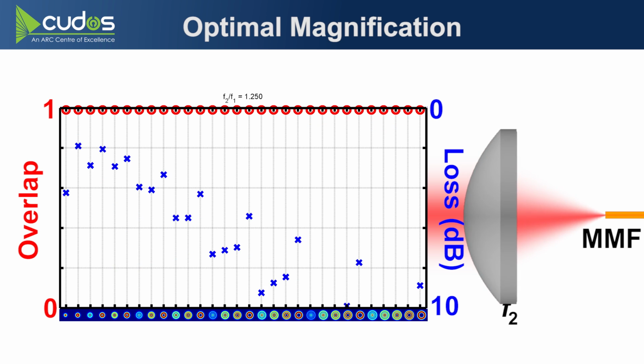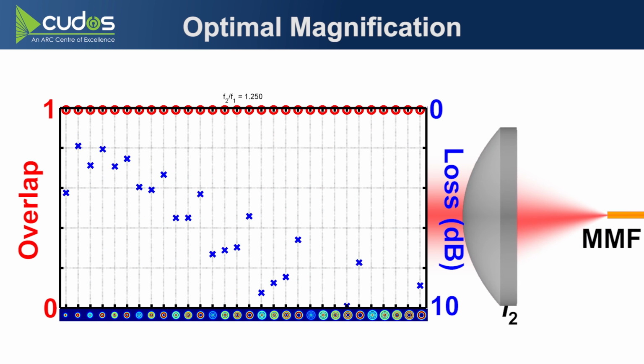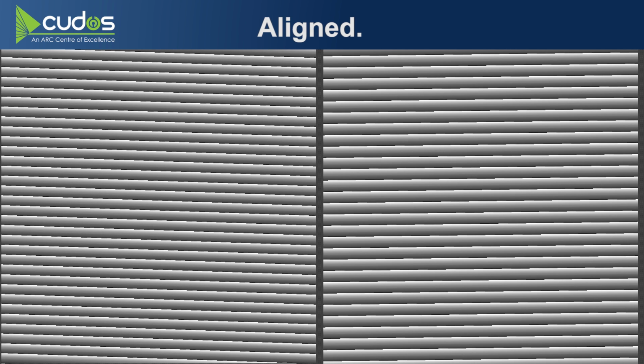Another convenient aspect of an SLM is that it allows you to perform a lot of the fine alignment of the system in software without moving parts. So here's a system attempting to find a particular output fiber by adjusting the phase tilt of a blazed grating for each polarization. And you can see that the two polarizations aren't exactly the same, and that's because my mirrors and beam splitters aren't exactly at right angles to one another. They calibrate that out.